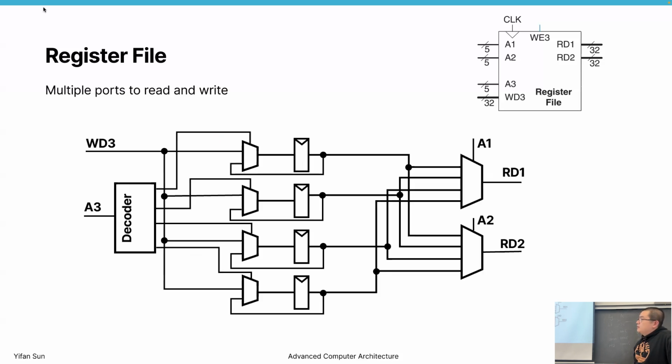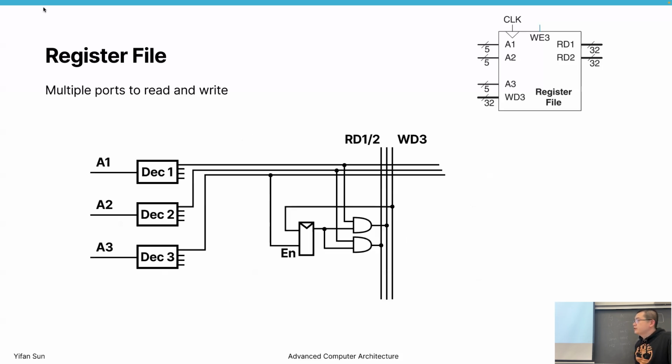This is one way. For CPUs, a register file implemented this way is generally okay. We're not that short on registers, we're not that short on die size, and we really want extremely low latency to read registers. And for GPUs, when our data is a lot, we have a lot of registers. Die size is a scarce resource. It's limited, so we don't want to use flip-flops.